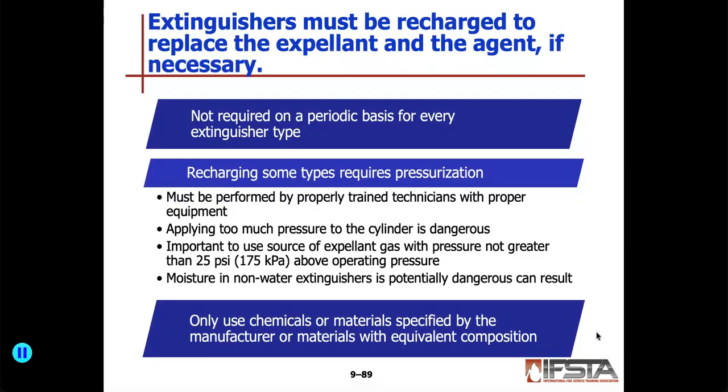Extinguishers must be recharged to replace the expellant and the agent if necessary. It's not required on a periodic basis for every type. Recharging some types of extinguishers may need pressurization, so that must be performed by a properly trained technician with proper equipment. Too much pressure makes the cylinder dangerous because you're overpressurizing a cylinder. It's important to use a source of expellant gas with pressure not greater than 25 psi above the operating pressure.